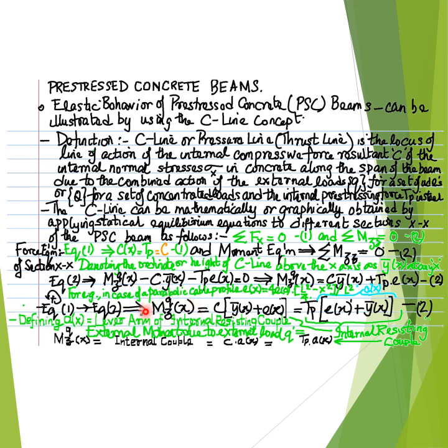The bending moment due to the externally applied uniformly distributed load Q, denoted as capital M subscript Z superscript Q, where the subscript Z signifies that the bending moment is about the Z-axis based on the choice of coordinate axis illustrated in the solved example presented in one of the earlier slides, may be equated or related to the internal compressive forces at capital C by this equation.